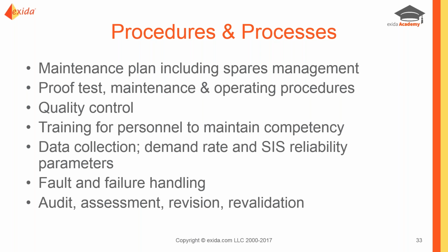And there can be different maintenance plans based on the SIL level. So obviously if we've got something that's a SIL 3, we may have a more rigorous maintenance plan or more redundancy, you know, 2 sets of eyes instead of 1 set of eyes type practice for some of these. So there could be differences in what those requirements are.